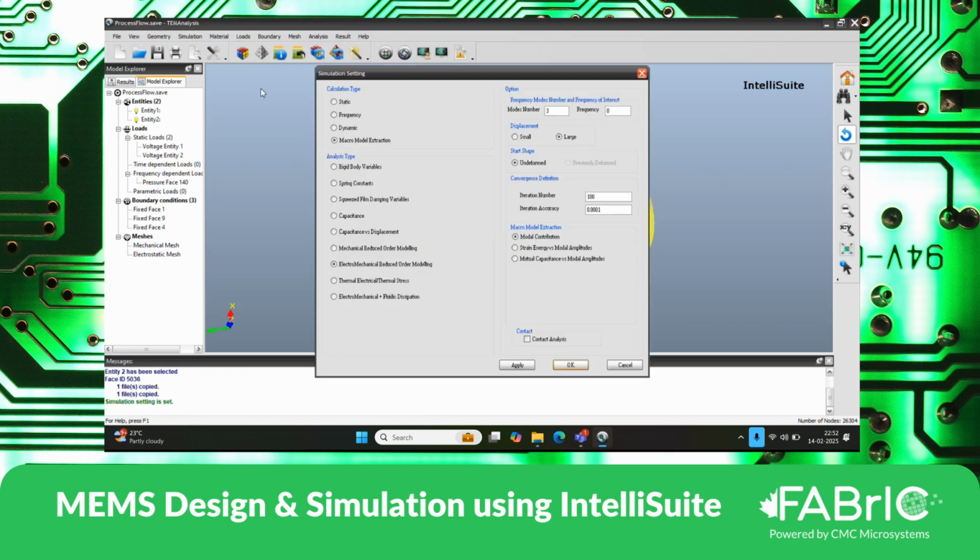Once we complete that, we redo the simulation in the same flow. We don't exit the module. Instead, we set the scale factor for mode 1. So what is the scale factor? The scale factor would have been generated in modal contribution, so that value is entered here. With that, the simulation calculates the strain energy versus modal amplitudes. This is for mode 1. Similarly for mode 2, mode 3, you can set the value.